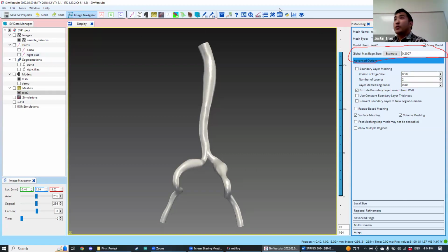Okay. Question. Yes. If the partially intersecting caps are only exterior caps, is that fine? Wait, what do you mean exterior caps? Mine comes up that I have partially intersecting vessels on the caps, but they're caps that don't intersect with any of the vessel. Oh, I see. So you do want to make sure that your entire model is one, and if you have a vessel that's off on its own, then you have to connect it back in. SimVascular will give you that warning if you have multiple inlets as well. So I think your model does have multiple inlets, and so you may be getting that error because of that. Otherwise, I think it checks to see if this vessel right here were sticking out a little bit, then it's going to give you an error for that as well. Not at connection points, they're at the ends of the vessels. Okay, that's fine then. I think it's because your model has multiple inlets, so that's fine.